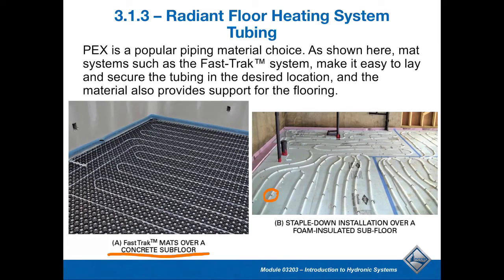It's really nice. It's a nice way to lay it out. An alternative method, and this is what I've done on my own systems, is I've used the plastic staples in there. So I have these foam staples I'll put underneath my slab. I'll put all of the foam insulation on there, and even notice on this picture, I want to point this out, you're going to notice on this system how they have insulation on the edge of the concrete.